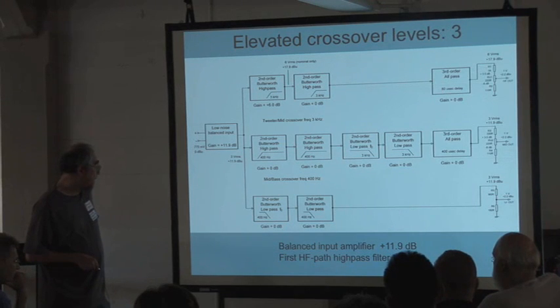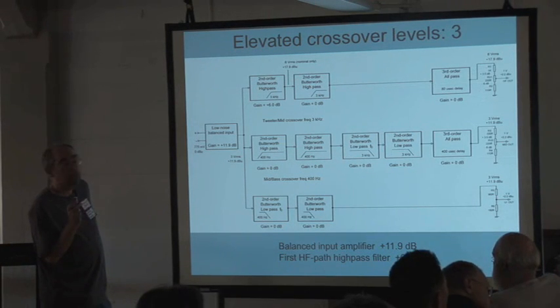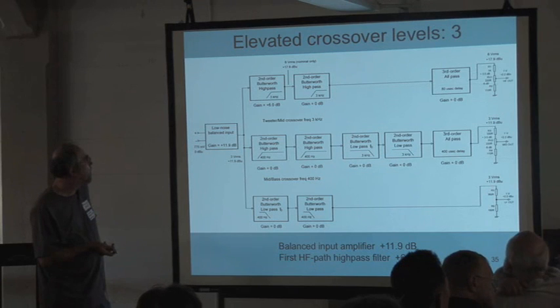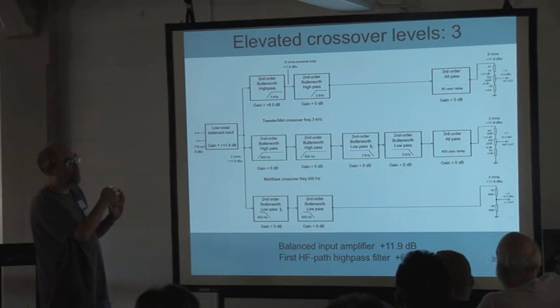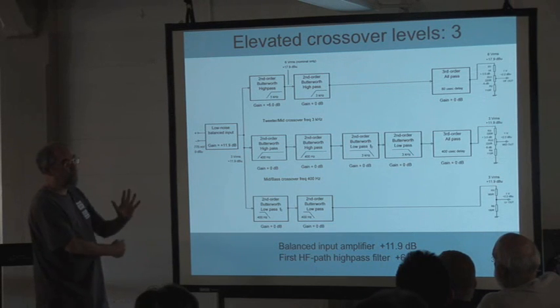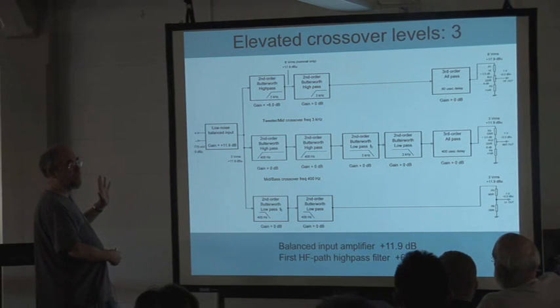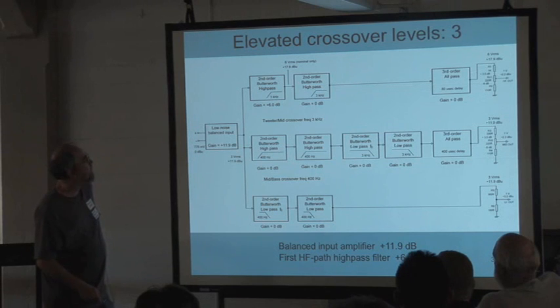Right. So. Question. Why is the tweeter not 480 milliseconds? Because the difference between the acoustic center of the tweeter and the mid is going to be a lot smaller than the difference between the acoustic center of the mid and the LF, just because the LF is bigger, and it's going to have its cone set further back. So that's just an average kind of value. I mean, it varies obviously with speaker unit and so on.